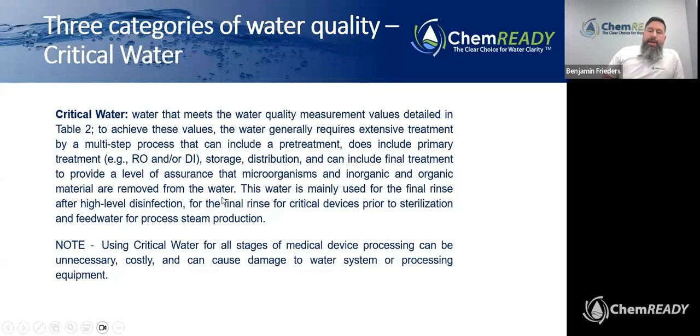Critical water is the water that meets the water quality measurements for typically the very final rinse or the final sterilization in your medical device processing step. Typically, it requires extensive treatment, multiple steps to include pre-treatment, i.e. softeners or carbon filters, reverse osmosis, deionization, and critical water also includes specific storage requirements for that water, the distribution loop that delivers that water, and then also includes final treatment that can include UV sterilization and endotoxin bacteria filtration that are removed as the final filtration step from the water.